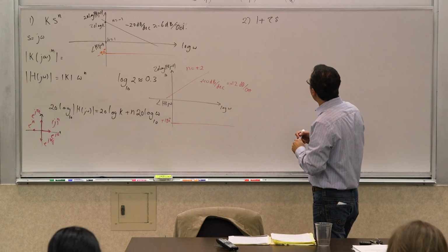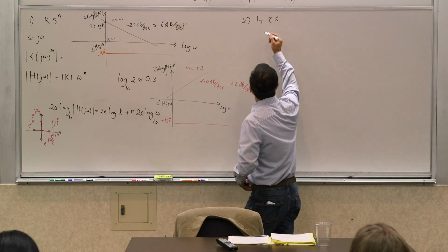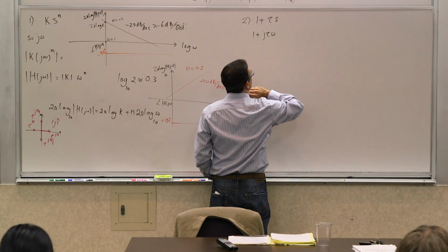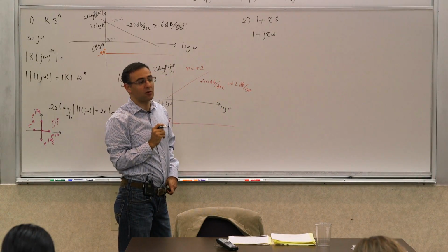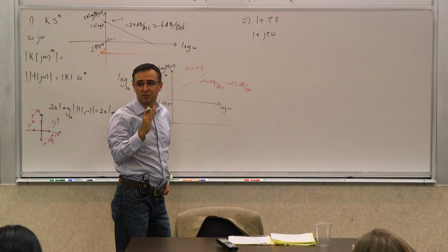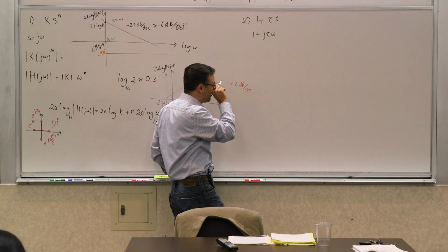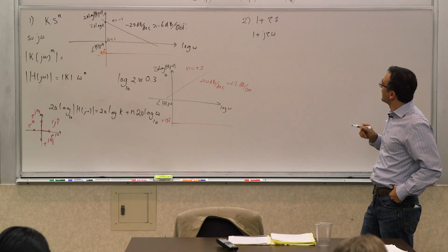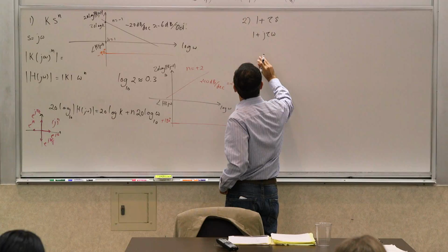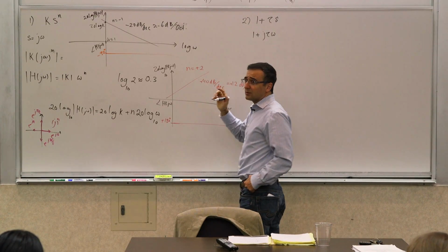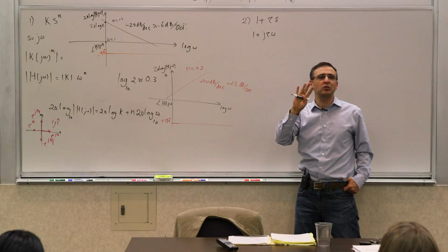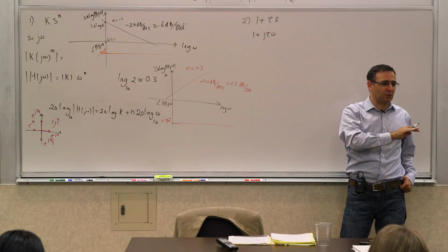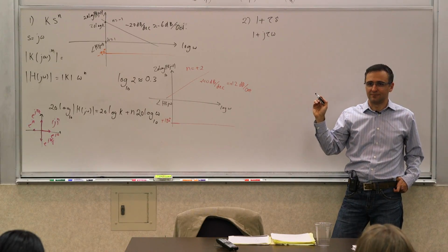So how does this look? First of all, we are really not looking at that. We're looking at this if you're talking about Bode plots, with s being j omega, because it's a very special kind of perturbation. It's not any generalized frequency. It's really specific, like sines and cosines, really. Now we can look at this and say, how does that look on a Bode plot? Let's look at two special cases. And this is what you do with Bode plots. You generate asymptotes, and once you know all the asymptotes, then you can generate the plot very easily.